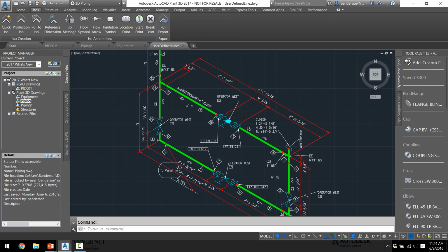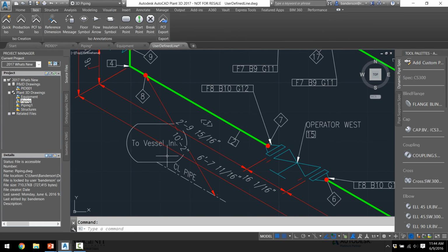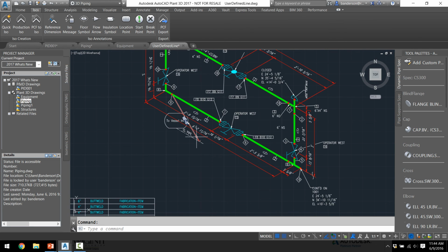As well, we can see that I've got that reference dimension, and that all of it can be moved. I've got that inlet. Now I could have taken the time to do a perpendicular snap to make sure this was all square, but you can also see that I can do skewed dimensions as well without any repercussions, and it'll still make sure that it displays it. Now there's still going to be some work to make sure that we pull this out and that it's displayed correctly, but as far as being able to reference this information and actively place this, I love this, because now we can say, oh, it's so far from the floor, and when the construction crews get out there to place this or actually install it, they know how far it is from that nearest beam or from the wall or from the floor. We have this reference dimension that gets saved into the model.